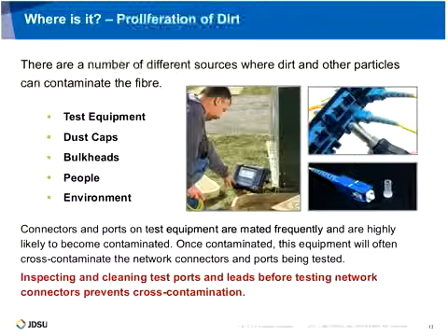I could tell stories from our service department where someone will send back a very precision advanced piece of test equipment like an OTDR for service, and after assessing it, our service department will determine that the service it needed was that the fiber connector on the test port was severely damaged because people were plugging contaminated connectors into it.